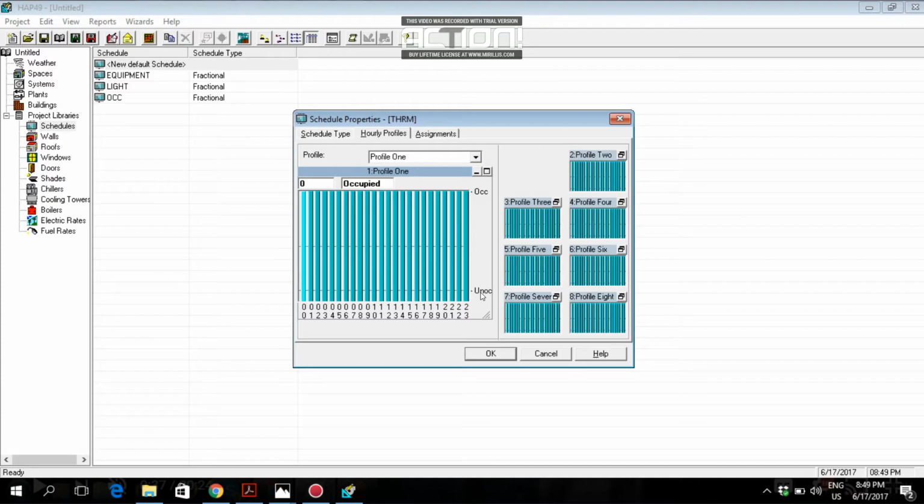So that factor is decided as OCC, occupied and unoccupied. Unoccupied means, for example, the temperature has already reached 20 degrees centigrade, so consider it as unoccupied. Occupied means the temperature is above 20 degrees centigrade, so it will be considered as occupied. Later on you will see what exactly it means. I will show you.